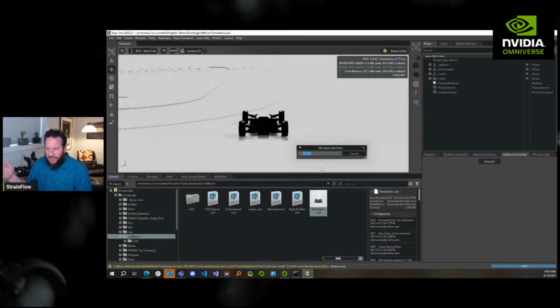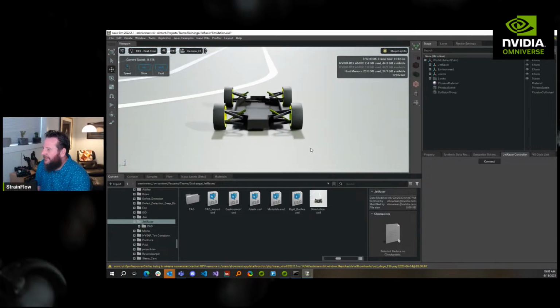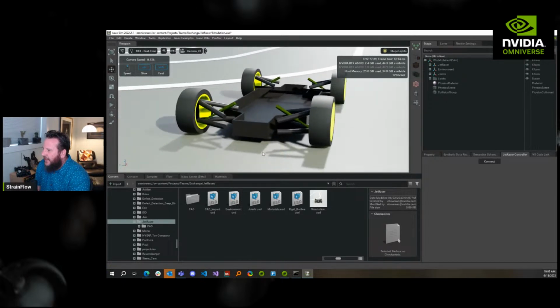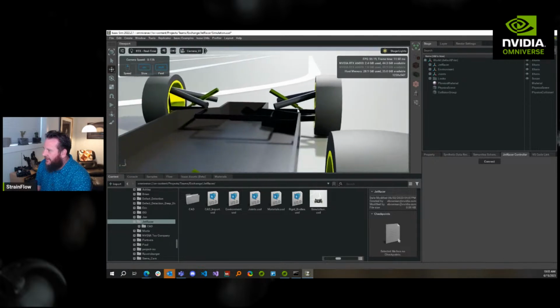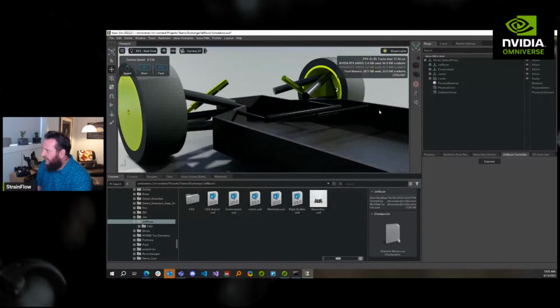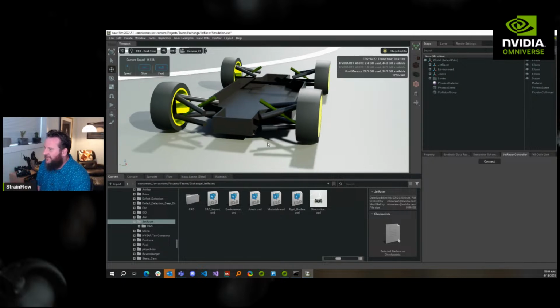So last week I showed you how to bring that stuff in. I showed you how to rig the suspension. I think I even showed you how to set limits on the shocks. And what I've done during the week since then is I went ahead and rigged up the other side of the suspension, the right-hand side. And I also did the steering here. And I looked up the units in Isaac Sim. My chassis really weighs like a kilogram, whereas the arms weigh like 10 grams. So I think getting some of those weights right helped.